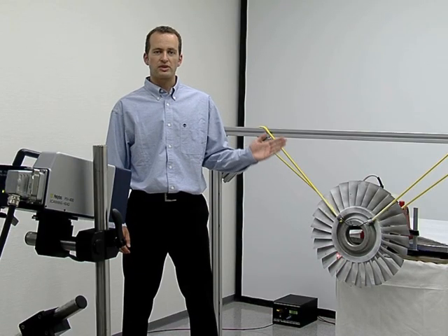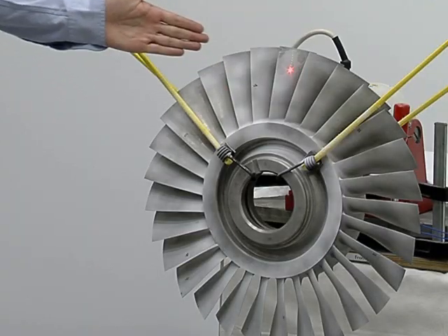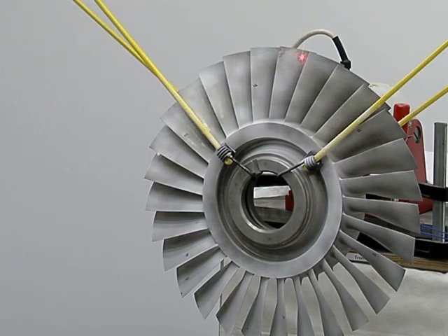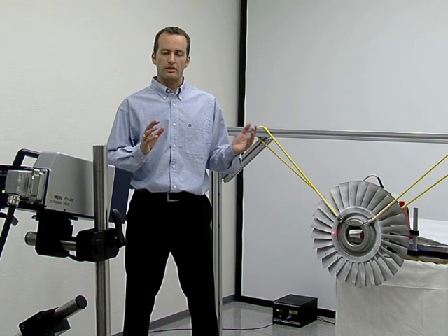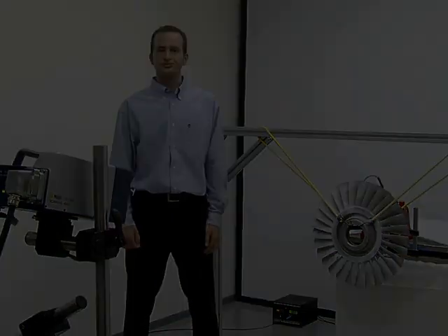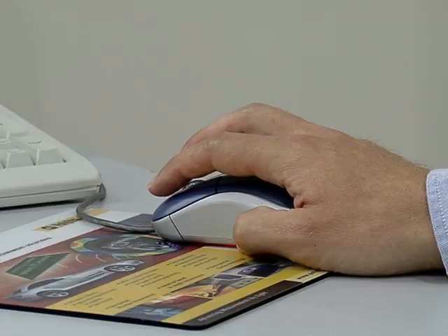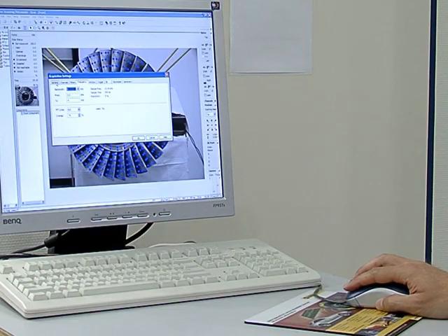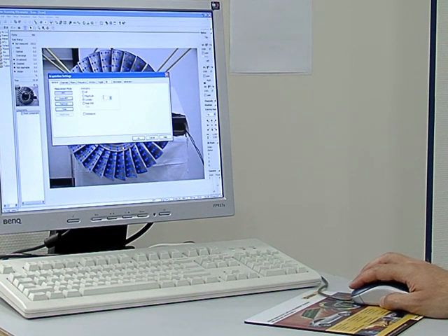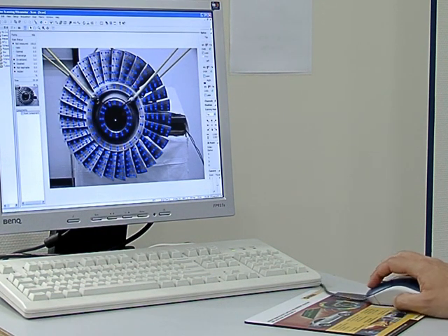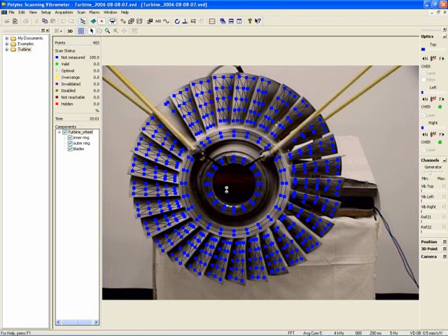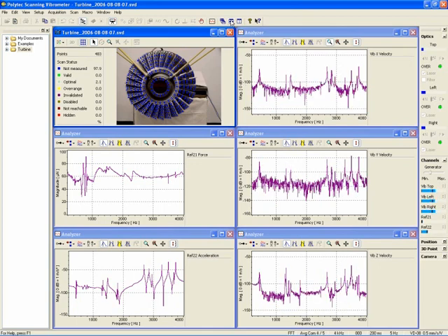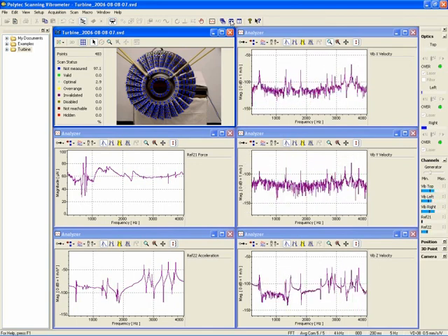During the measurement, the beams are scanned synchronously across the surface of the measurement object, simultaneously acquiring the three components of the vibration vector at each scan point. The measurement time depends on the settings for frequency resolution, number of averages, and of course, on the number of scan points. In any case, complex objects can be characterized with several hundred to several thousand individual measurement points in a very short time, especially when compared to traditional contact transducer methods.